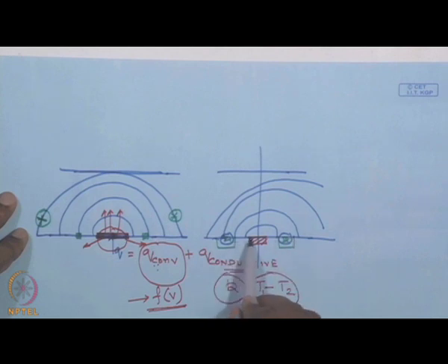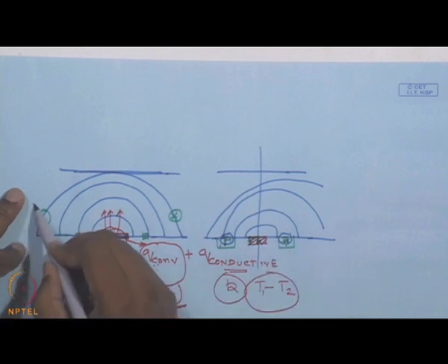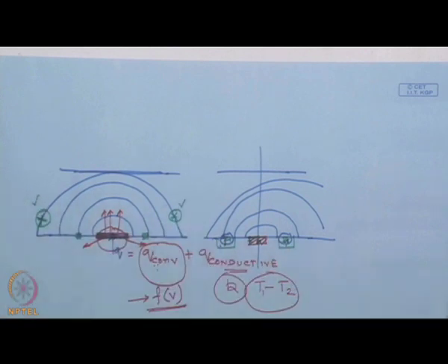As we understand, with increase in flow we lose more heat through the sensor, so these solid temperatures should also vary, and the variation of the solid temperature will provide us the knowledge about how much heat is being lost. So, it's a much better method to measure the temperature of the solid compared to the temperature of the fluid.